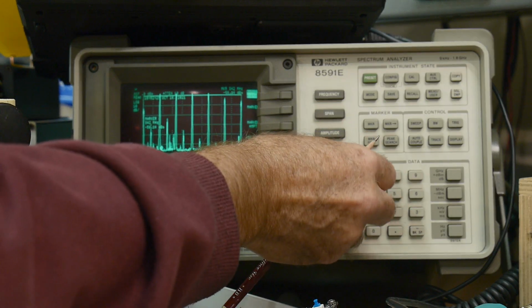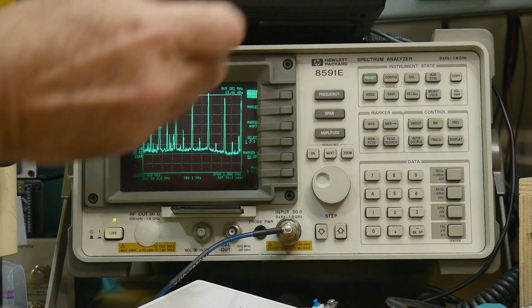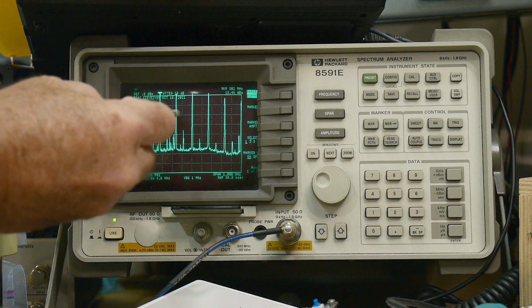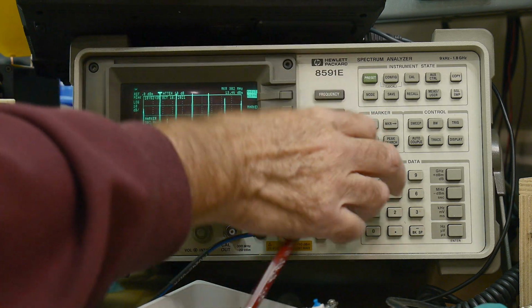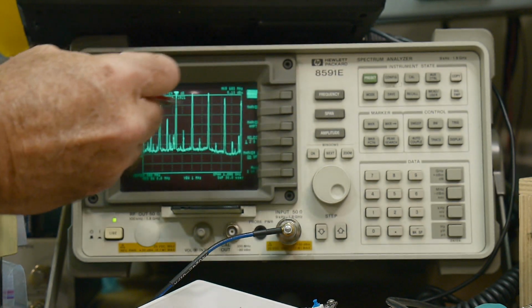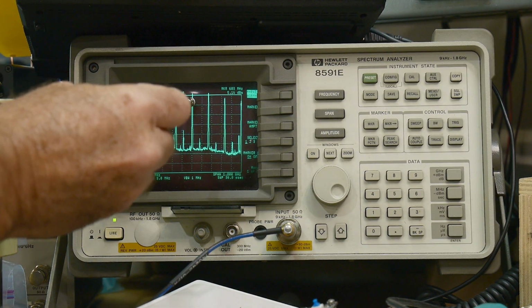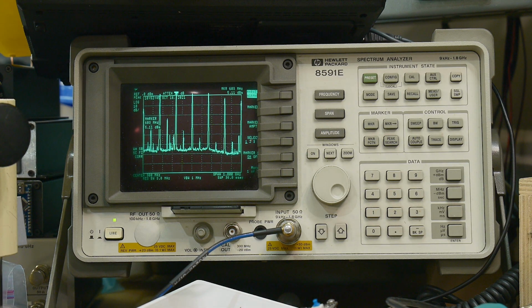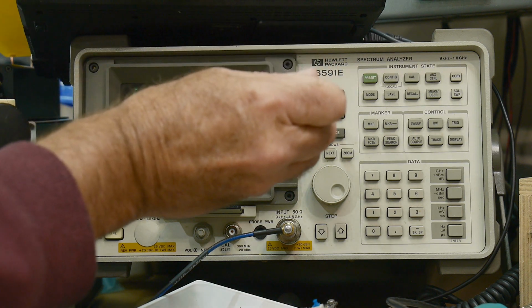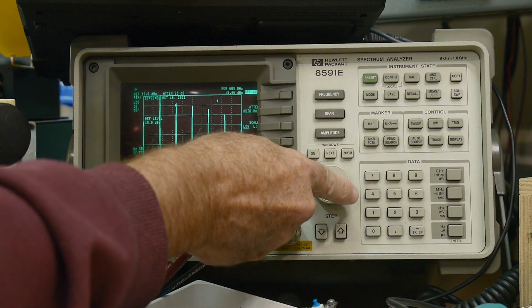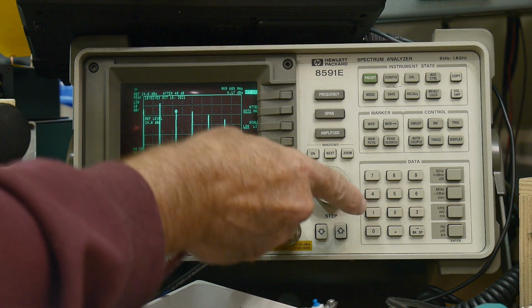let's see. So this marker, this is the 300, and there's the, it's probably 900. Yeah, no, it's 600. So 300, 600, 900, 1200. Yeah, it keeps going up. So, and those harmonics, let's see here. Let's change the reference level down so we can see everything. There we go. That's better.